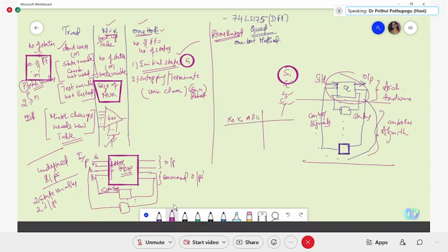That means it is the sum of the state variables and the inputs that defines your table size. Now in the traditional approach, with the same two state variables and two inputs, you had a choice of defining some don't cares, something like the unused state variables, we were taking them as don't cares. But here there is no chance of putting don't care.